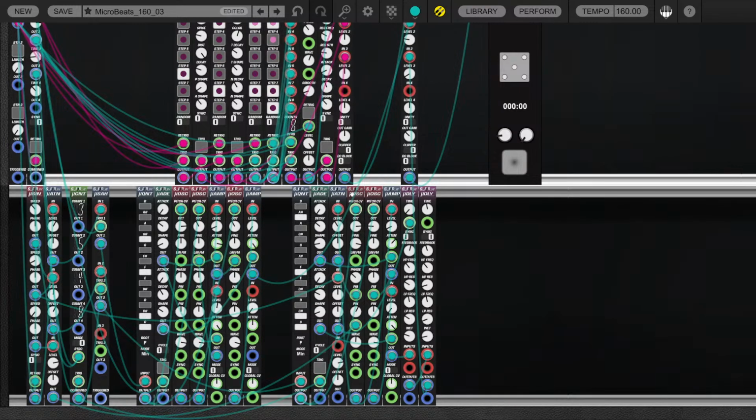For the melody we basically do the same. We have 2 oscillators here. Interesting thing is that the modulator is outputting a signal into an attenuator, which in turn gets fed back into the phase modulation input of the modulator itself. So this is feedback phase modulation.